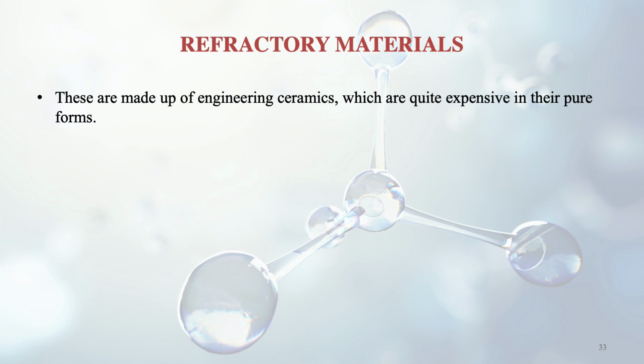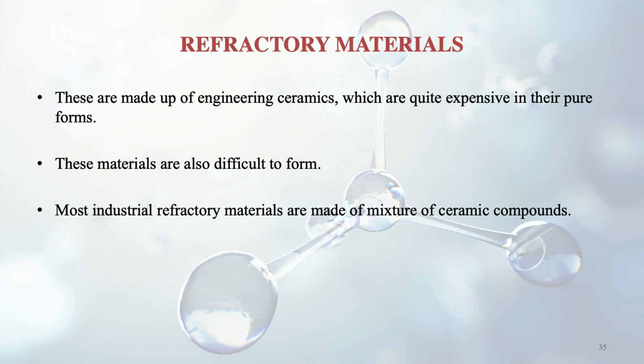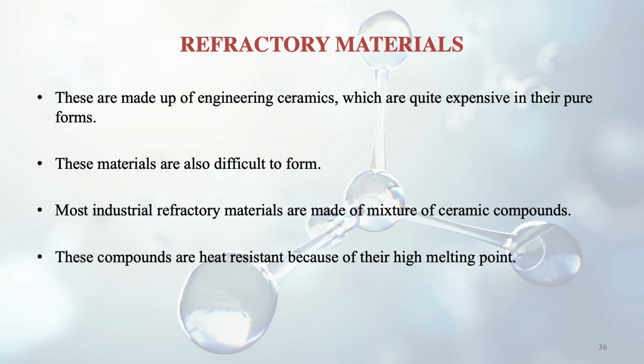Further, we are discussing certain refractory materials. These are made up of engineering ceramics, as we have discussed earlier, but they are very expensive in pure forms. These materials are also difficult to form. Most industrial refractory materials are made of a mixture of ceramic compounds, and these compounds are heat resistant because of their high melting point.